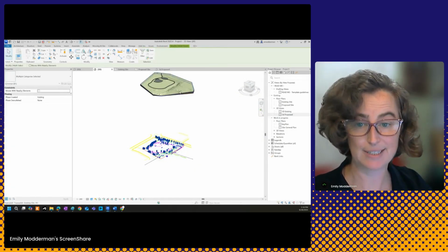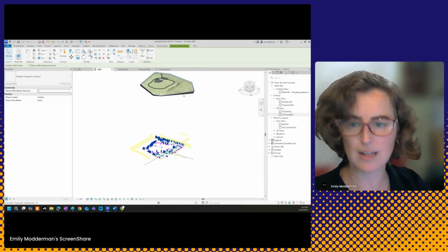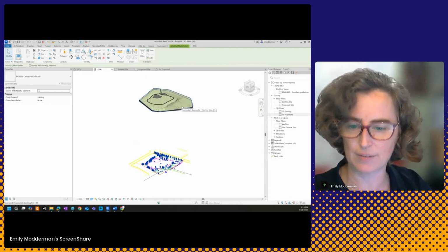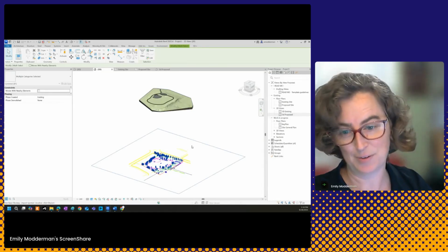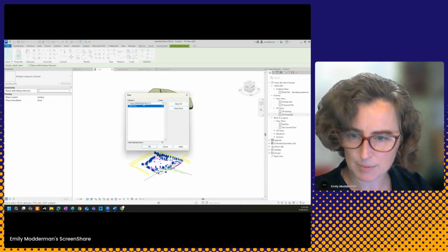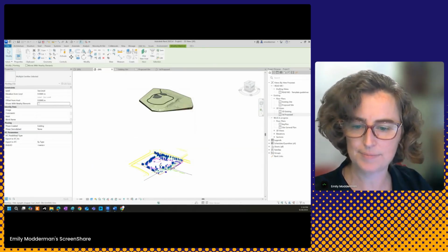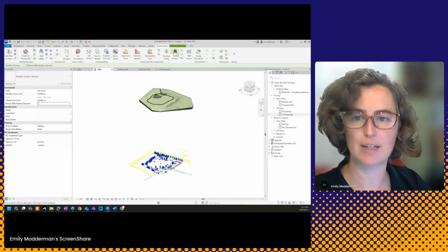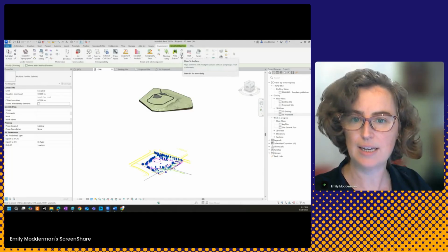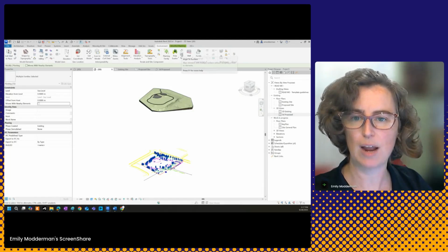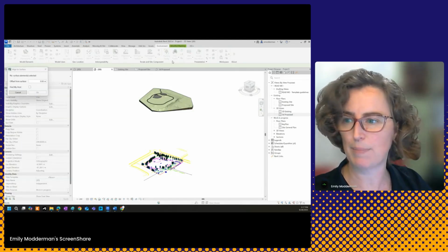Now, my site's up here at its real sea level elevation. You know, this is 500-ish or 300-ish above sea level. And my trees are down at sea level. What do we do? Well, first of all, I'm going to filter that out because I seem to have some line work in there, so that I only have my planting families. And I'm going to go to the Environment tab, and I'd like to align these to a surface, that surface being my topo. So I have this terrific little tool, Align to Surface. I'm going to pick those up.